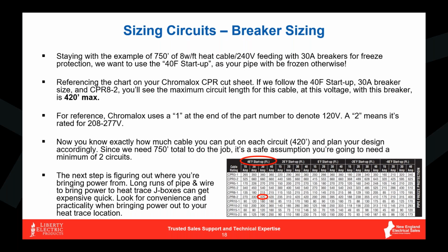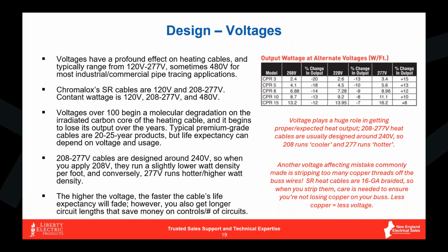So really, when it comes down to it, a lot of the design is going to vary tremendously in terms of where you want to bring power from, where you can bring power from, and where we set up that first, say, J box and start on that pipe tracing. So a lot of this will require some collaboration between both the specifying engineer, possibly the rep if they're helping out with that design or doing the design for everyone, and then of course the installing contractor, so that you get all your ducks in a row and we all know where power is coming in, and we can lay out that design from there.